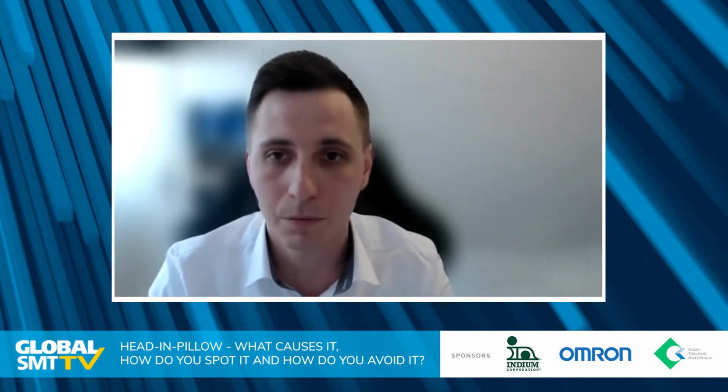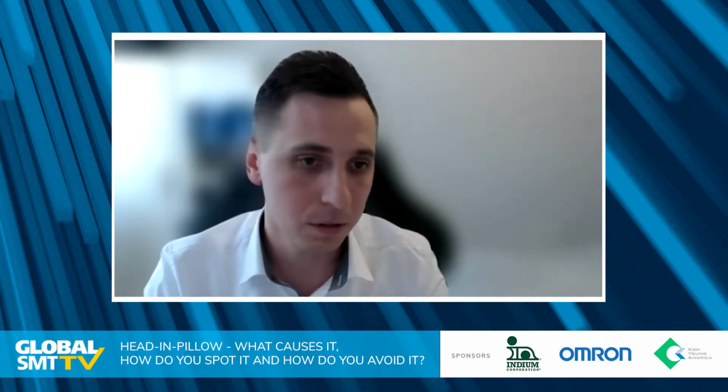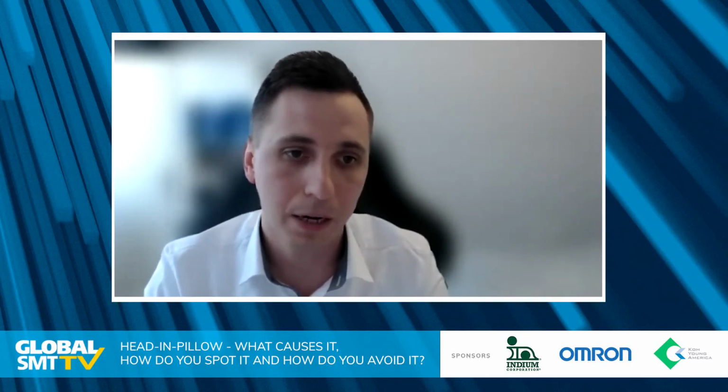But okay, fair enough. So let's look at what are the primary causes of head and pillow defects. Piotr, do you want to kick us off with that? Sure. So basically, there are many reasons for head and pillow. Some of them have a bigger impact, or smaller. I guess there are two most important causes, and one of them is the package warpage.